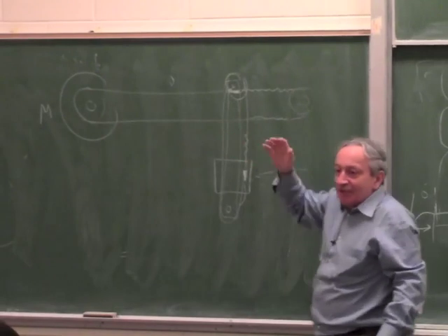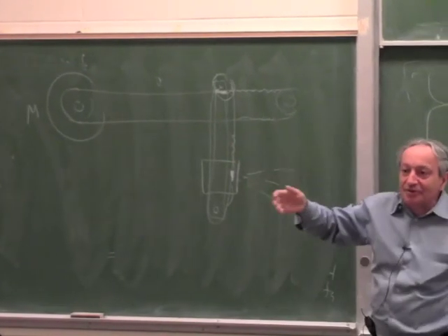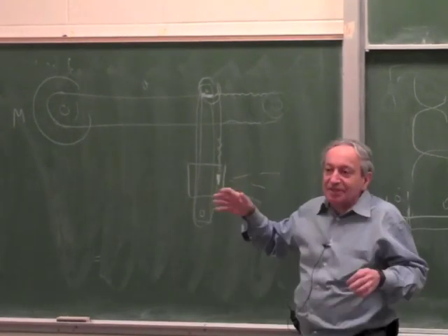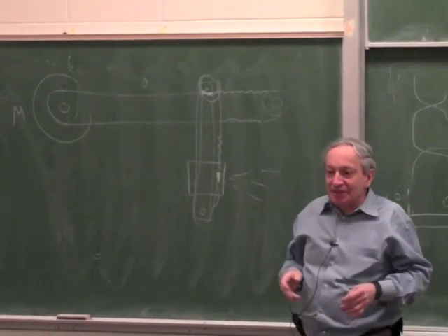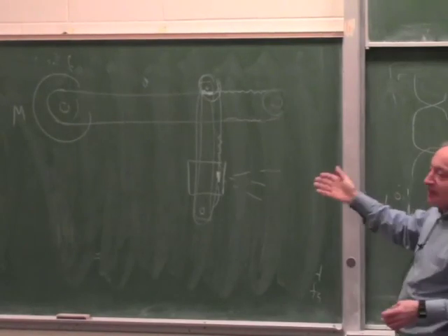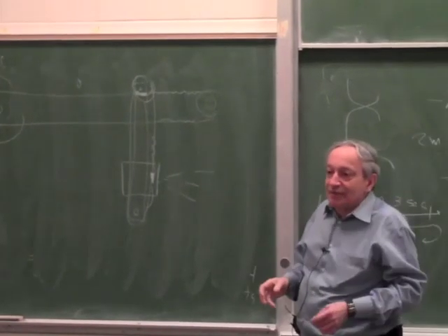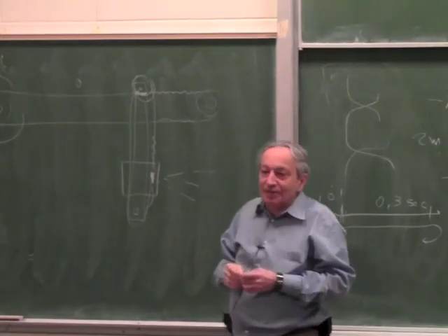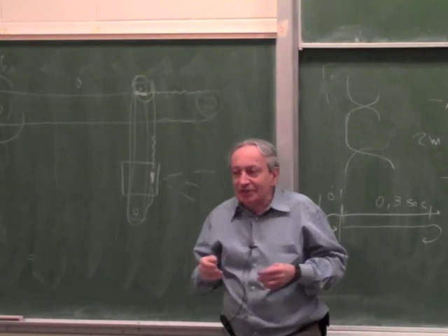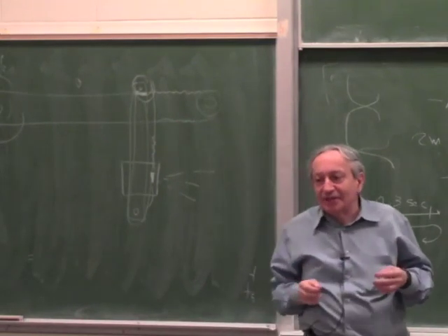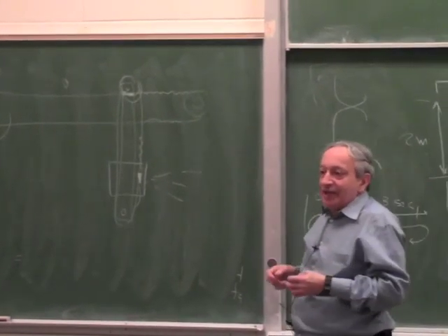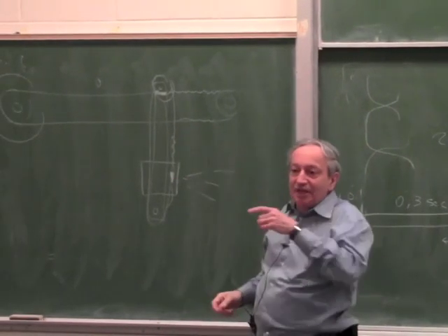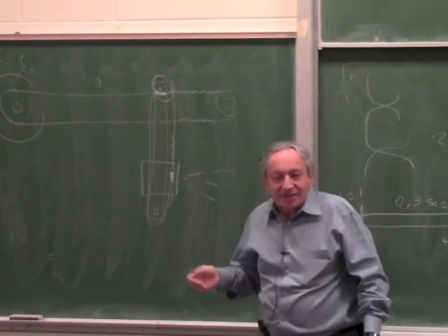Okay? I mean, you can argue that you can use a linear motor, but it's much more expensive. So again, whatever you say, as long as it makes sense, is acceptable. The right solution in a case like this is actually a timing belt. But if you say, I want to make it pneumatic, I want to make a long air cylinder, that's fine. Or if you want to say, I want to make a special lead screw, as long as it's not crazy, it will be accepted as the correct answer. For example, a steel cable. Instead of a timing belt, you can take a steel cable or a steel ribbon. That's acceptable. Okay?